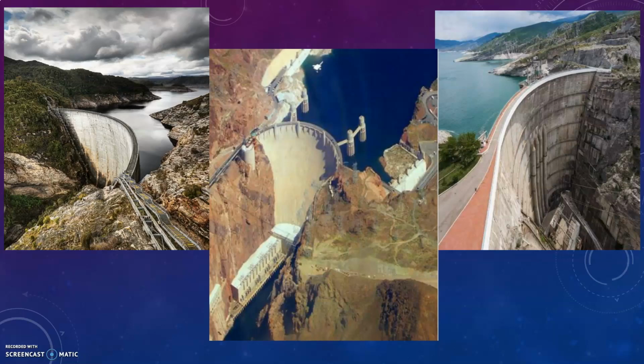There are some disadvantages. It requires skilled labor and sophisticated form work. The design of an arch dam is also quite specialized, and also the speed of construction is normally slow. It requires very strong abutments of solid rock capable of resisting arch thrust. Hence, it is not suitable in the locations where strong abutments are not available. Unfortunately, only few sites are suitable for this type of dam.